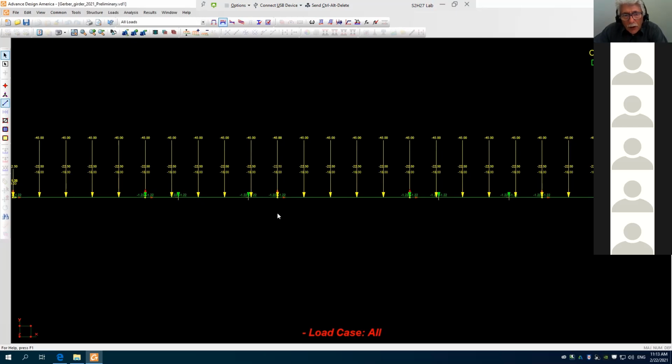If you want to be more precise, I know what you're saying, Alex. What did I do in my loads that you found incorrectly? On your snow load P3, you placed one of the loads on, I believe, a 2.2 meter member, which should have been starting on the 10 meter member. So is this my file?